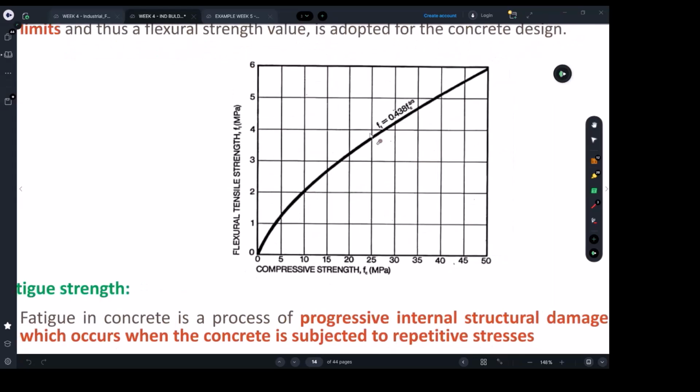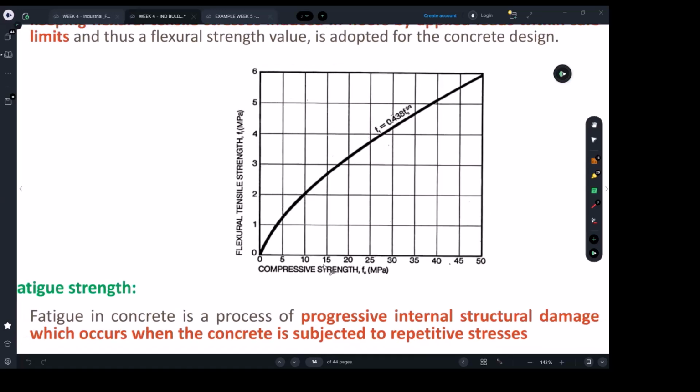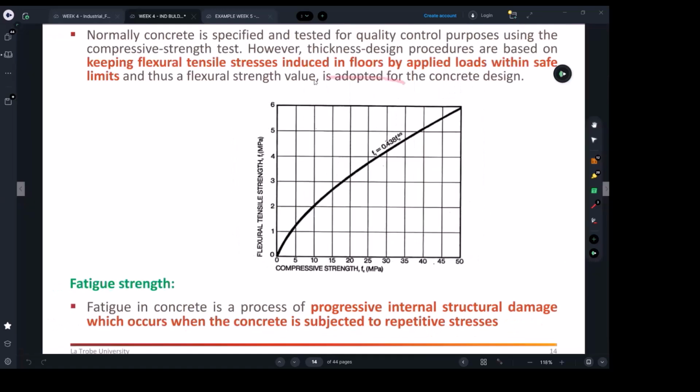It gives you an idea about, if we don't have steel in the slab, what's the maximum tensile it can take. So this is just telling you the flexural tensile capacity for the concrete itself. And that's where engineers will start thinking about putting steel to make it resist more. Regardless, as I said, there is minimum steel. You can't see a pavement slab with zero steel. This is not possible because there's shrinkage.